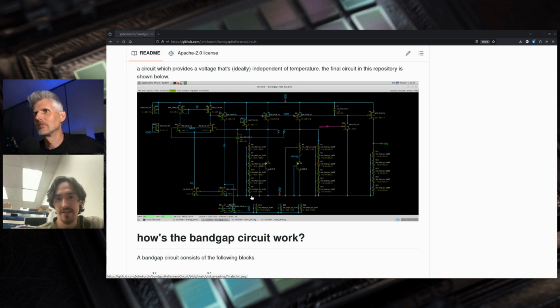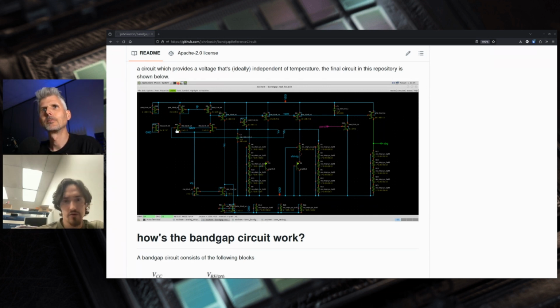Yep, unit. Yeah, as a student, I'm taught to use unit-sized devices and copy and paste those entire units rather than mess around with the sizes. Yeah. Again, that's for better matching and performance across different process variations, right? Exactly. Okay, so then this is what you use, and does this include dummies as well? Like these are dummy? Exactly. Yeah, everything that is necessary to pass the final true LVS that would go through the tape-out process. Okay, so these are all dummy resistors and transistors. Yeah, exactly.